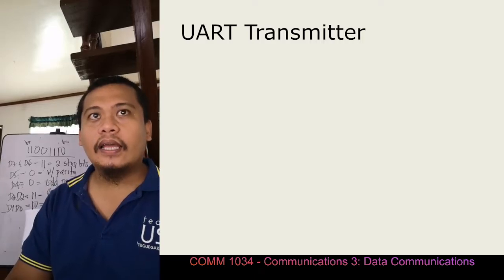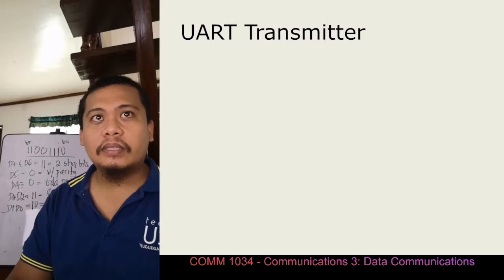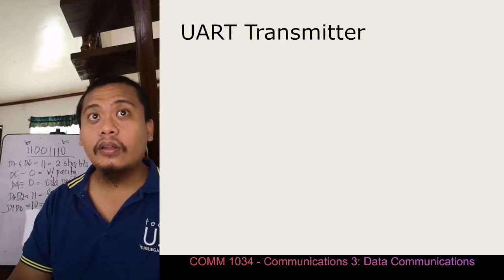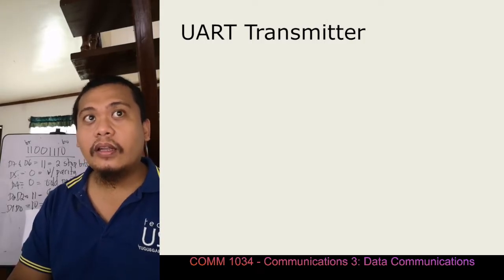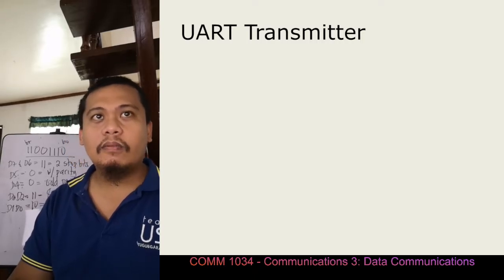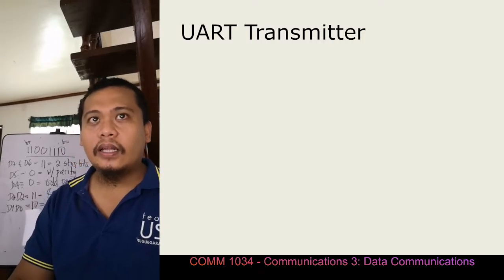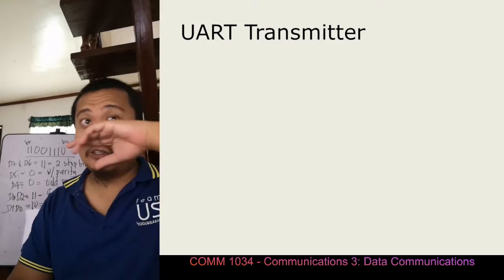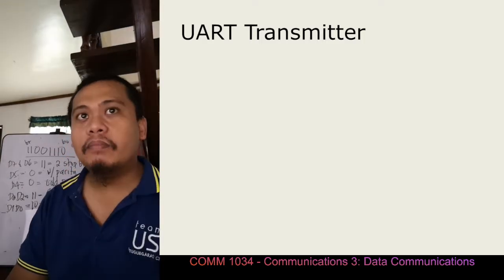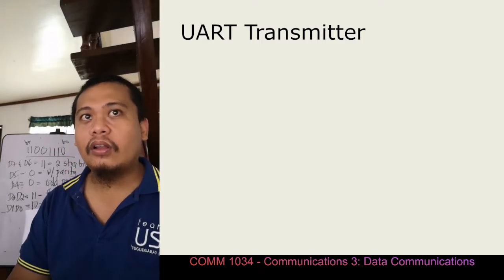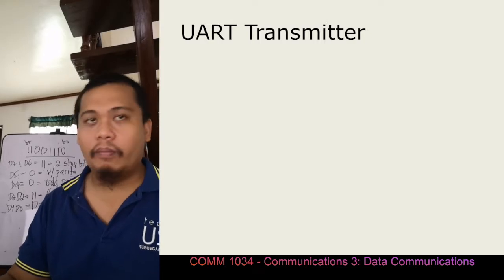However, the UART can send or receive data. The UART control register must be loaded with the desired mode instruction word. So this is accomplished by the CPU in the DTE, which applies the mode instruction word to the control word bus and then activates the control register strobe.